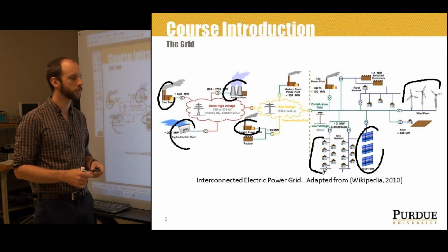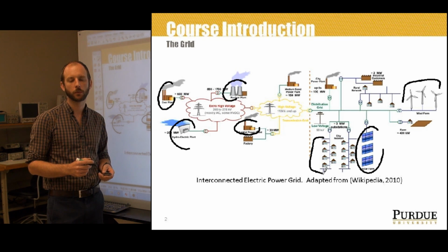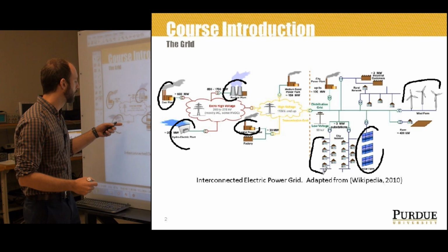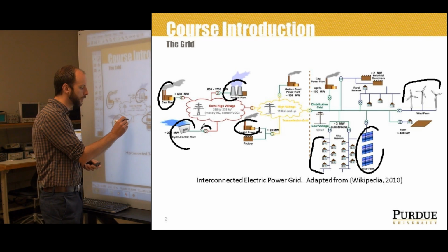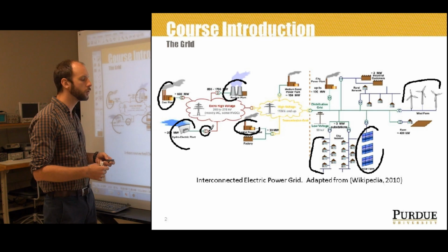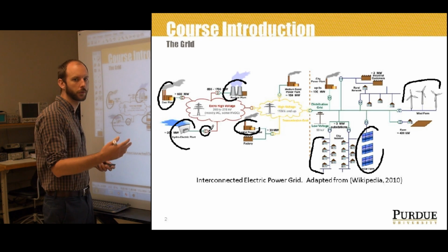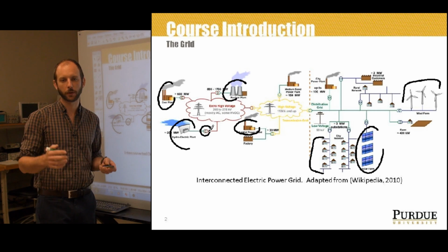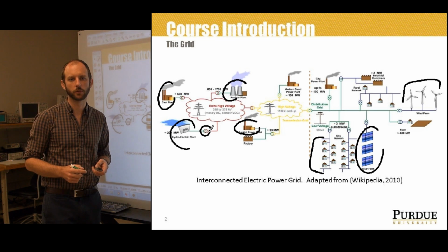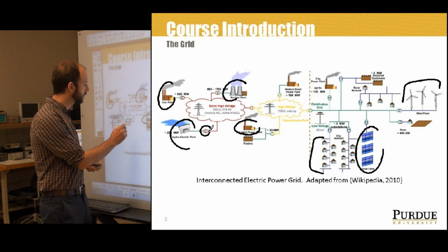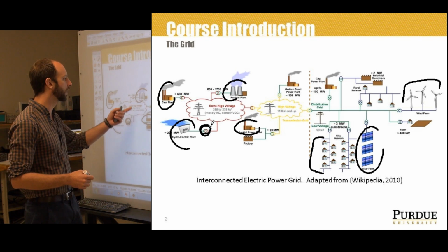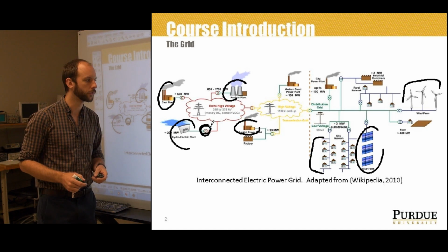They produce a low voltage. The output voltage of these generators, in terms of power systems, is low. It's at 20 kilovolts, or 20 kV. Those low voltages are then stepped up at the generation to some higher voltage for transmission. We're going to say usually it's bigger than 69 kV if those voltages are traveling long distances. There are some special considerations that we'll look at over the course of this class, but really probably about 69 kilovolts to transmit over long distances. And that's done by these step-up transformers, taking the generator voltages and increasing them to some sort of higher voltage.